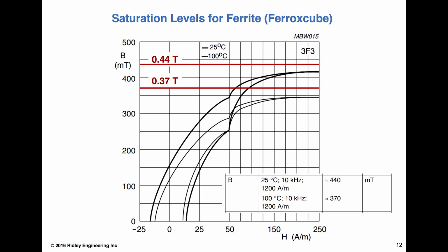We have some planar PCB magnetics. Somebody asking whether you can apply a planar PCB to multi-kilowatt. Absolutely, yeah, it's been done. Some of the first planars I ever saw were done at IBM for their servers 25 years ago, and they just had a great big E-core with a bus bar running through it.